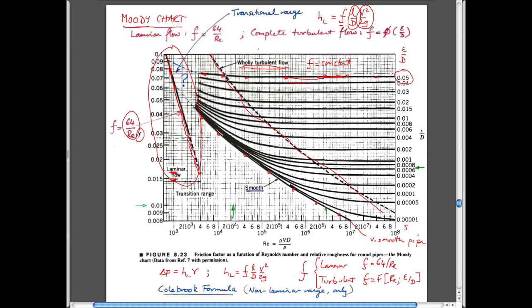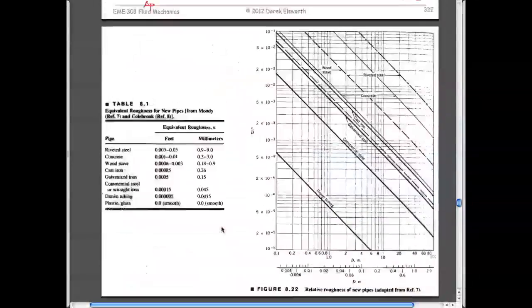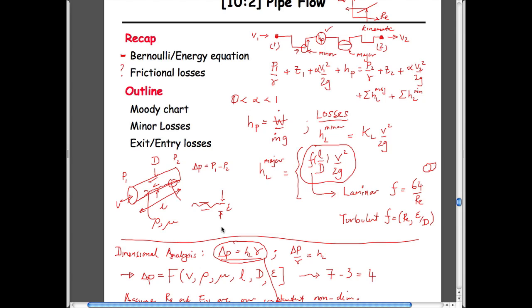then this transition to turbulent flow happens much earlier than if you have really smooth walls. Right? This Reynolds number here is very high. For a very smooth, infinitely smooth tube, it happens at a very big Reynolds number. But for a relatively rough walled tube, it happens at a relatively small Reynolds number. And so we'll use that in the coming sessions to be able to usefully use this expression to figure out exactly how we solve for these pipe networks, which say something about how much fluid we can put along for a given amount of energy.